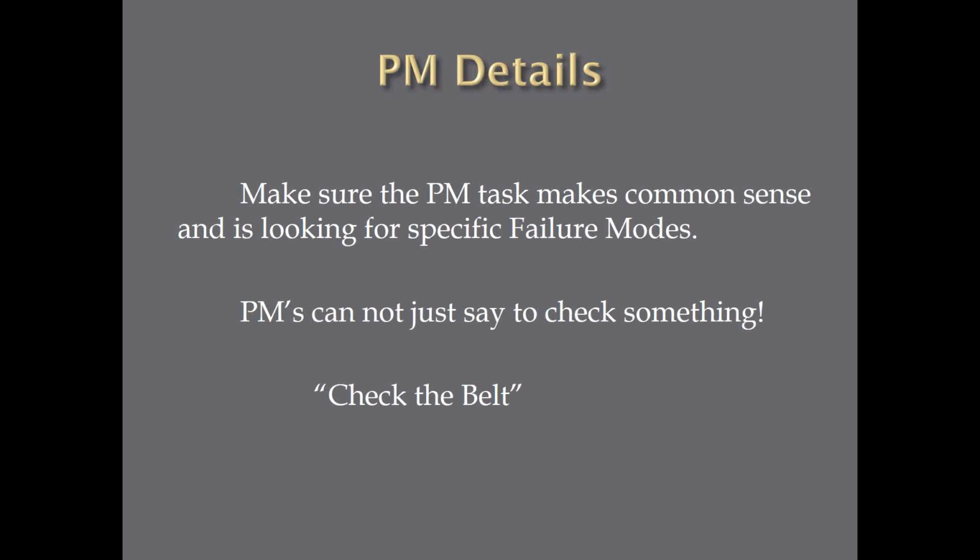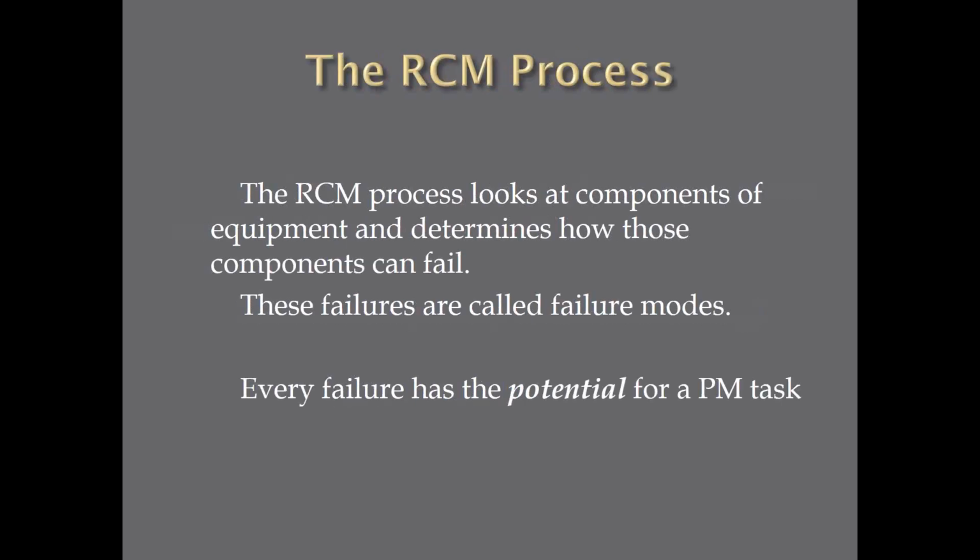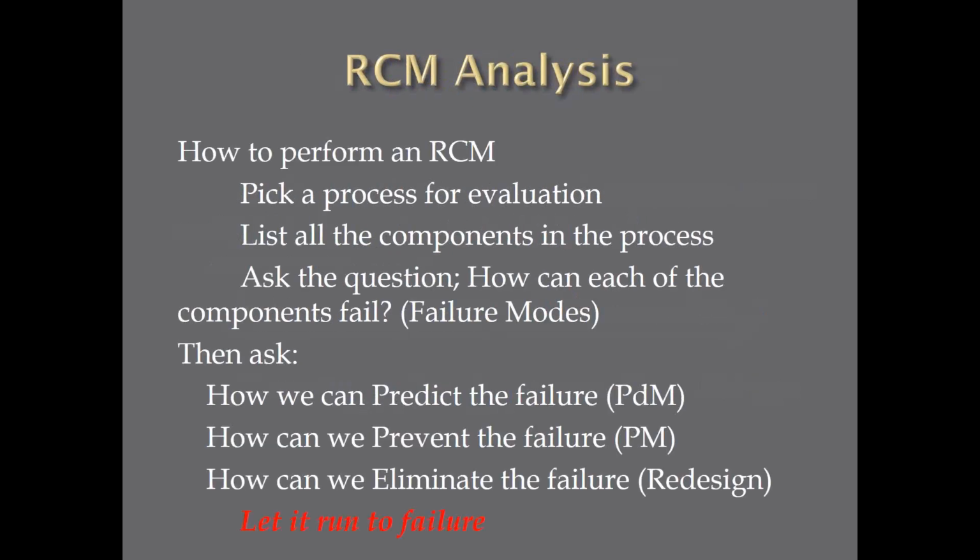What is he actually looking for? So these are called subjective PMs. The RCM process looks at components and equipment, determines how the components can fail. In RCM, these particular failures are called failure modes. So every failure has the potential for a PM task. But again, we have to look at why we do the task, what's the cost of loss, what's the downtime. Maybe if there's none of those things, we wouldn't do the PM task.